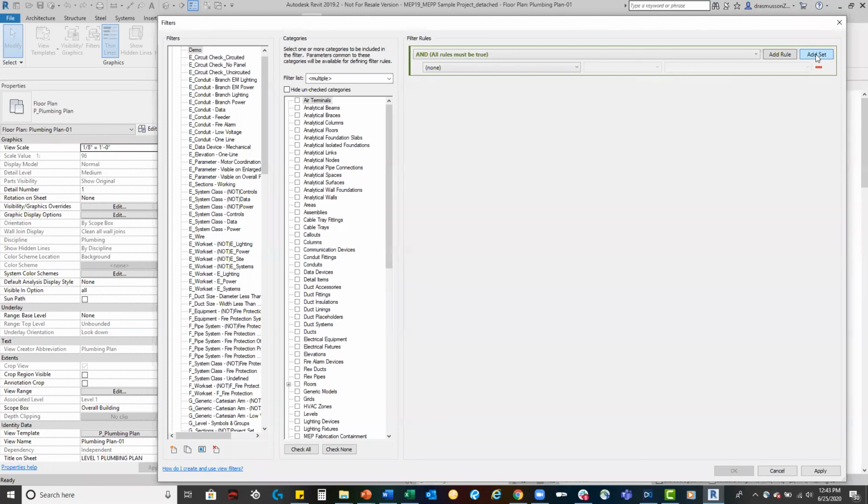Great question. Piping and demo create some challenges for us, especially if we want to demo half of a linear length of pipe, for example. Obviously, Revit is tuned for you to use the phasing controls. So demo is an action that occurs at a phase. The MEPPP is set up to leverage that.